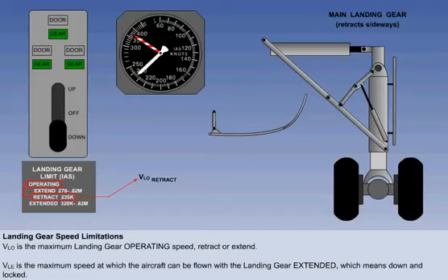The landing gear is normally retracted as soon as possible after takeoff to reduce drag and increase the climb gradient. There is no normal requirement for the gear to be operated at high indicated airspeed, so the retract and extend mechanism, together with the attachment points to the structure, are sized for the required task. To design the gear to operate at high indicated airspeed would needlessly increase the structural weight.